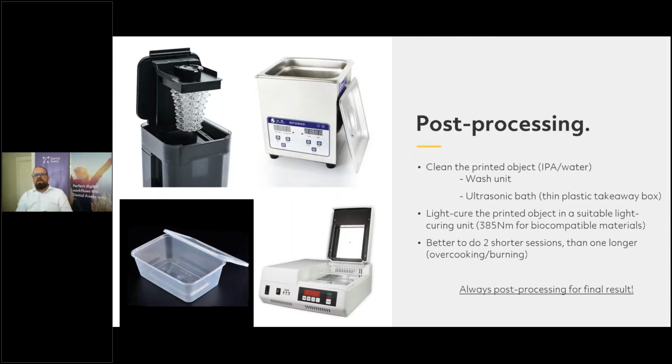And one of our really good tips is take your build platform on your bare arm and rub, basically slide it on your arm, because the skin on your arm is very sensitive. So you directly feel if there is something still stuck to the build tray, which you haven't seen, for example. That's a really good trick to use. You're really sure, okay, that feels smooth. Fine, I am sure that my next print will be possible.